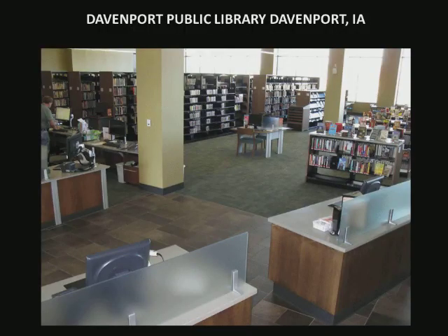Here we have another shot of the Davenport Library. Again, an excellent application for displacement ventilation. We have a high cooling load just from all of these windows that we see in the background, not to mention a vaulted ceiling of maybe 16 or 18 feet tall. We're not concerned with cooling that full 18 feet, though, as we would be with a mixed air ventilation system. With the displacement system, we're only worried about the first 6 to 7 feet.